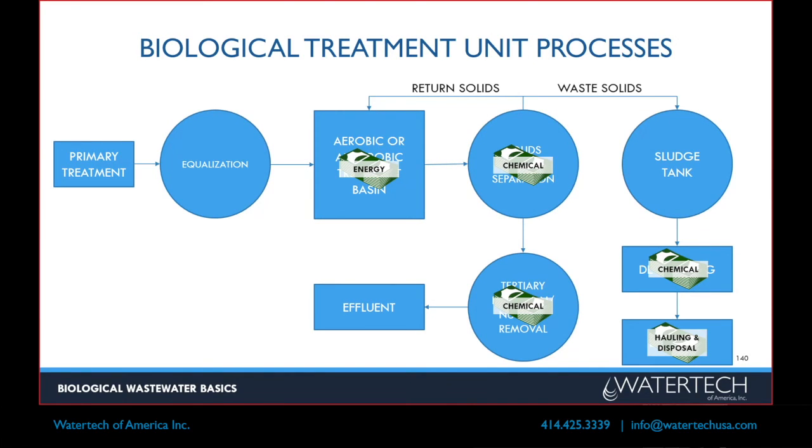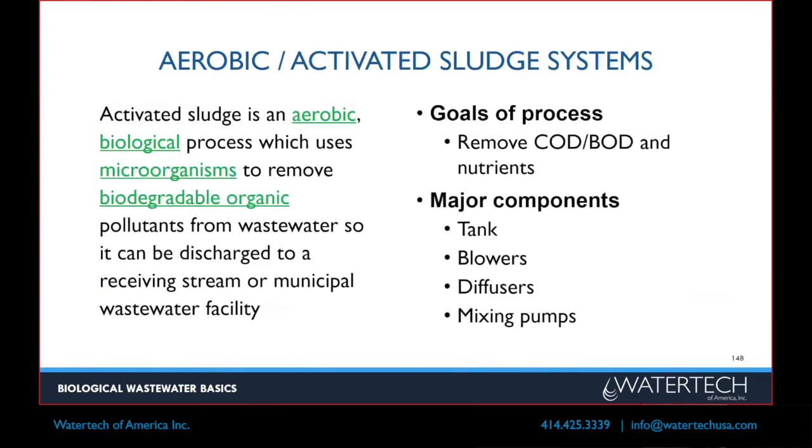The other thing that's nice about them is a lot less footprint than a conventional gravity clarifier will require. So if you're landlocked, you don't have a lot of space to add a whole new gravity clarifier, something like that, then they can be a good benefit. So that's one of the new things that's out there.